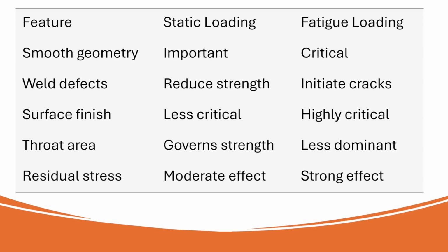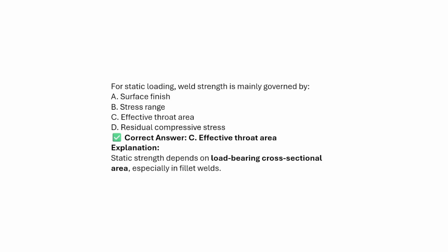The throat area governs the strength in static loading and is less dominant in fatigue loading. Residual stresses have a moderate effect on static loading and a strong effect on fatigue loading. Okay.